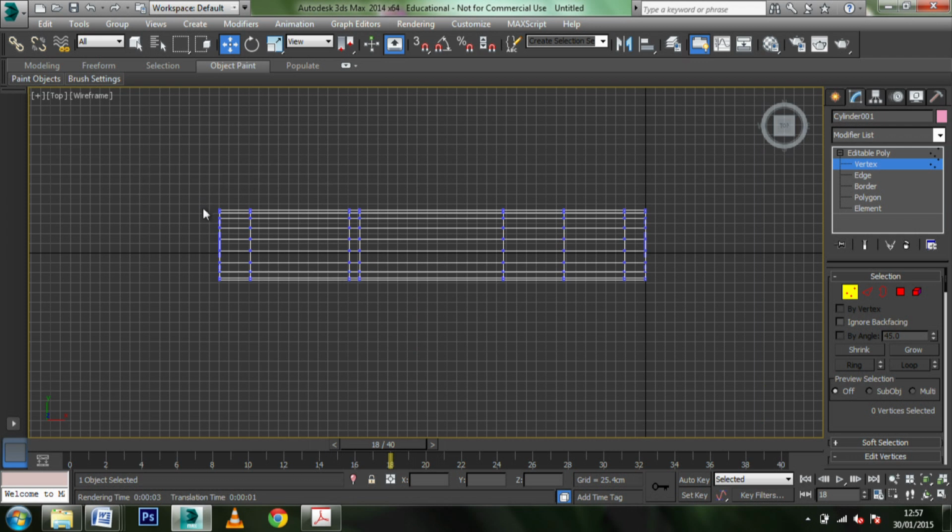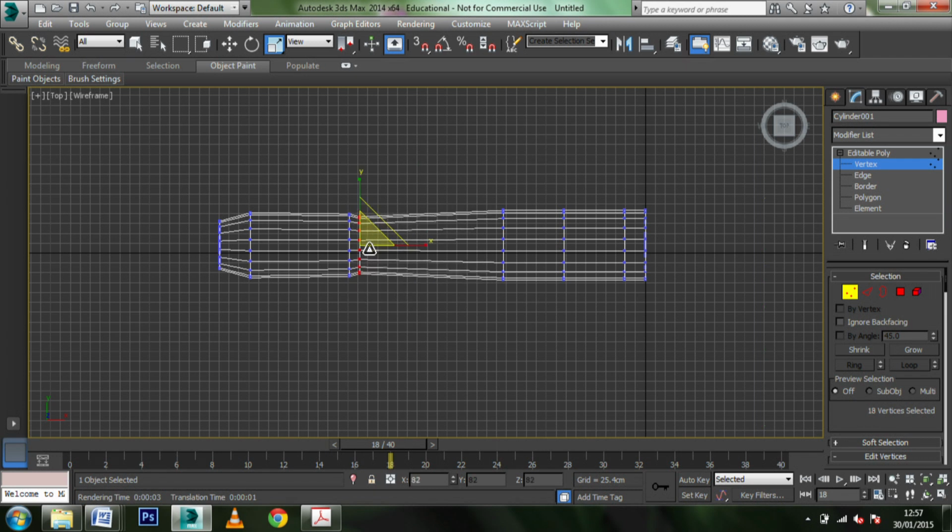So what I'm going to do now is get the cigar-shaped scaling for a model done. So I'm going to select the scale tool. I'll select the very front of my plane. I'm going to scale this right down like this. And I think this is the start of the cockpit, so I'm just going to scale it down slightly. This is the back of the cockpit, and now I'm going to start to taper away so we end up with that nice cigar shape of a plane fuselage.